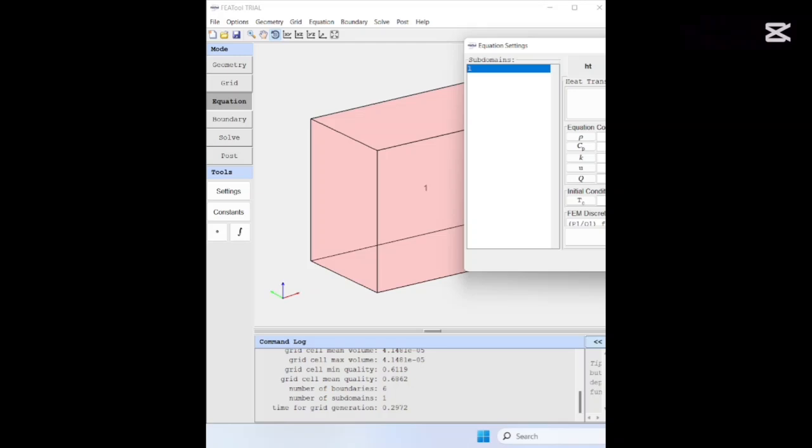We assume the PCM that is going to cool these tomatoes starts at the outside temperature, so you assume what the temperature for tomatoes should be within the Nigeria region, for example. Nigeria temperature is around 35 degrees Celsius, so you put 308. We are using Kelvin, because Featool uses Kelvin as its temperature unit.